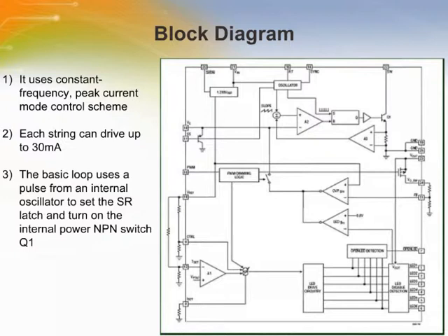The switch is then turned off, causing the inductor current to lift the SW pin and turn on an external Schottky diode connected to the output. Inductor current flows via the Schottky diode, charging the output capacitor. The switch is turned on again at the next reset cycle of the internal oscillator. During normal operation, the Vc voltage controls the peak switch current limit and, hence, the inductor current available to the output LEDs.